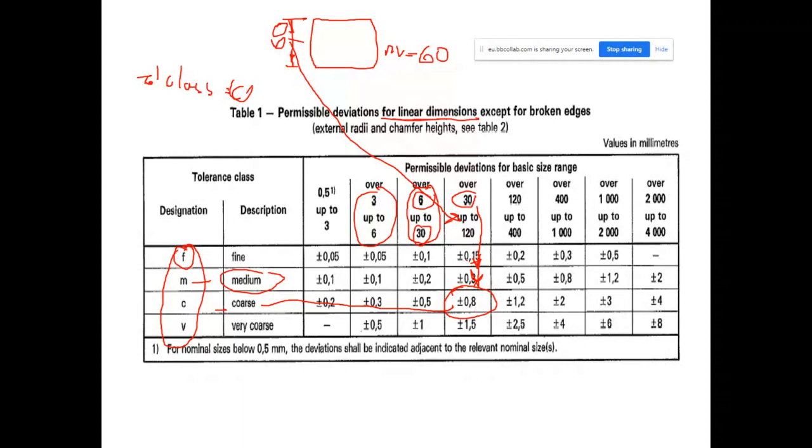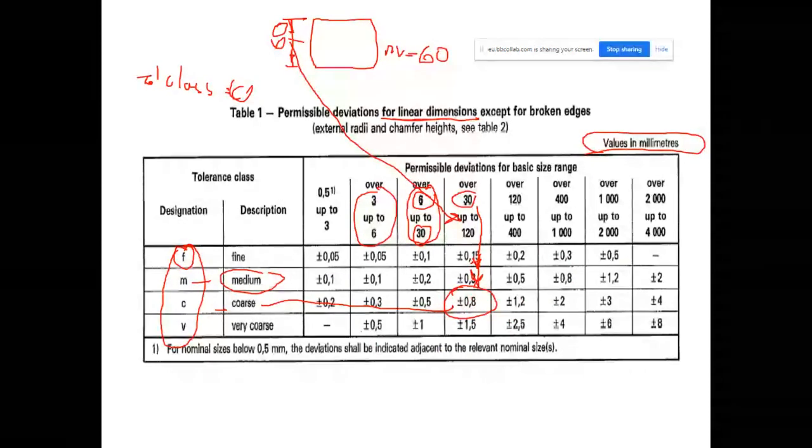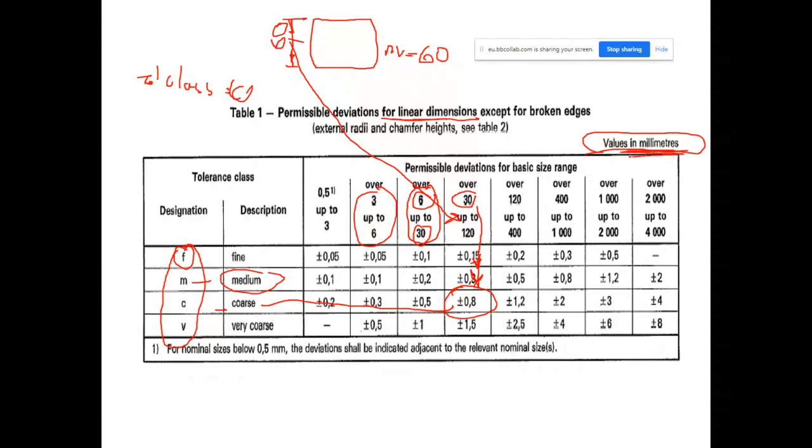And the pigeon box, the written numbers, all the pigeon boxes, written numbers are in millimeter. There is no trick in this table. The deviations in the previous table are in micrometer, but the deviations in the tables within this document are all in millimeter. It is written as it is written. So, well, in our example, upper deviation is equal to plus 0.8.